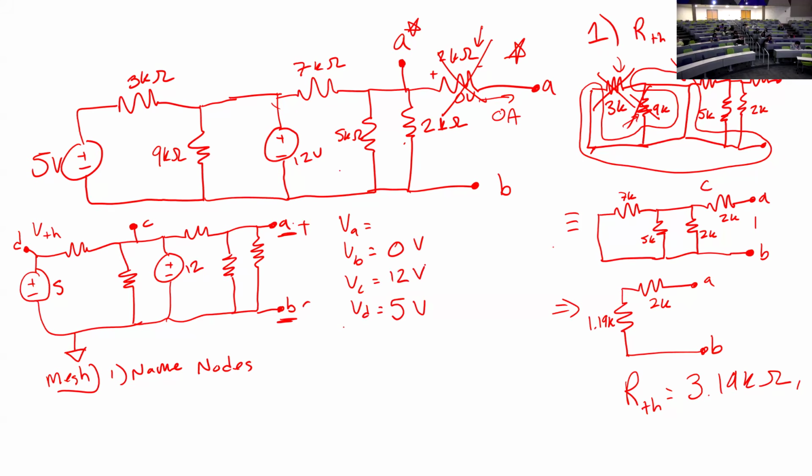All right. From here, we only have one node left, right? So here you could continue to use your node analysis, which I will do, but let's get this to be 7 kiloohms, 5, and 2. And the other important thing here is list plus and minus for your components, okay? Plus, minus, plus, minus, plus, minus.